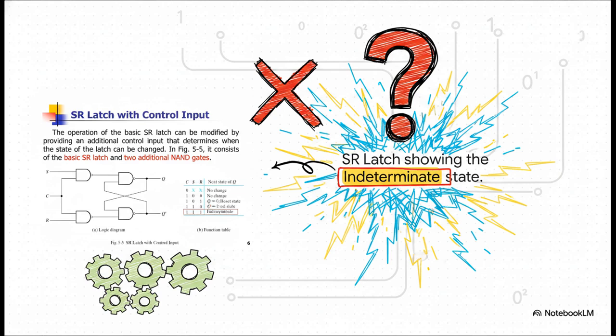We've added a control input, C, to our SR latch so we can govern when it changes. But look at that bottom row outlined in red. When both S and R inputs equal 1, we hit what's known as the indeterminate state. The circuit gets completely confused. This is a massive hardware vulnerability, and frankly, it's something we absolutely cannot allow in reliable computer systems.